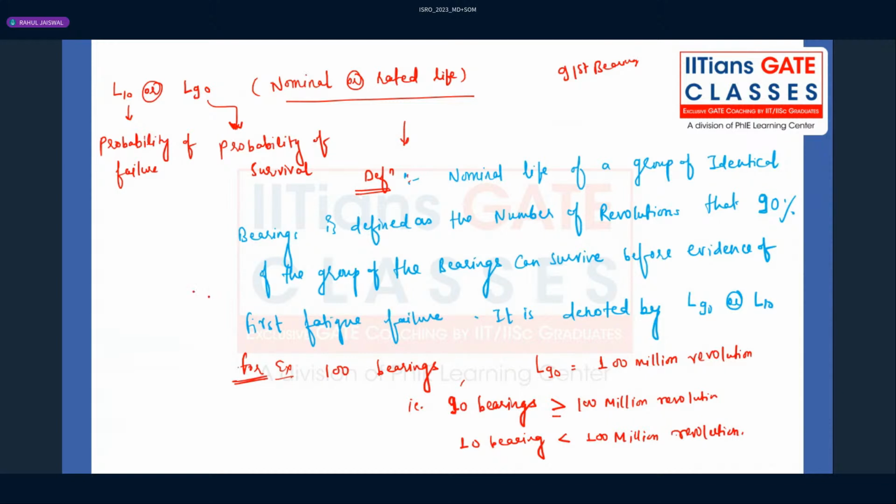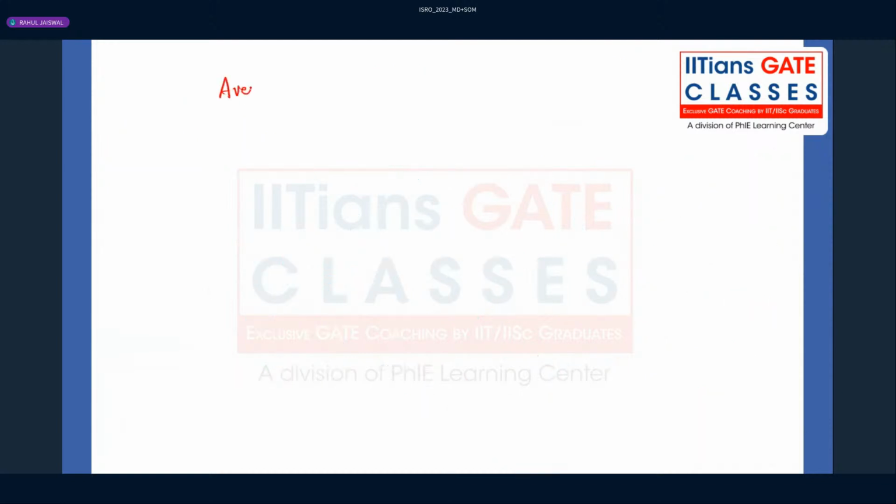Then, sir, what is the average life? Average life we define as L50. That means 50% of the group of the bearings. And automatically, my dear friend, it's very common sense: average life will be larger as compared to the 90% bearing life, because for that we are waiting till the 91st bearing fails. Getting my point? So obviously the chances are that the life will be lesser as compared to this life.